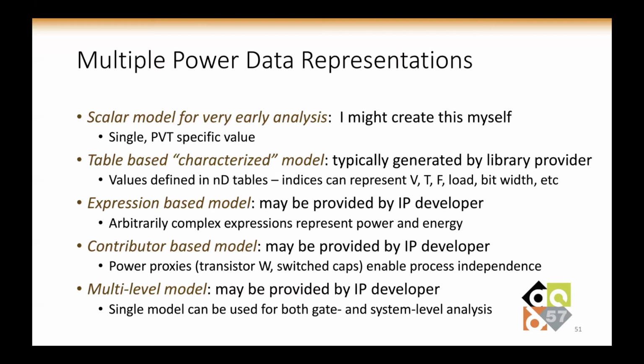Expressions may be arbitrarily complex and can be used for both static and dynamic power. Expressions are particularly useful to me as an architect, since I can often analytically model the power effects of different architectures without necessarily first implementing those different architectures. Contributor-based models are of great interest to me due to their PVT independence. I can estimate the PVT effects on leakage with expressions, but the contributors will provide the best accuracy.